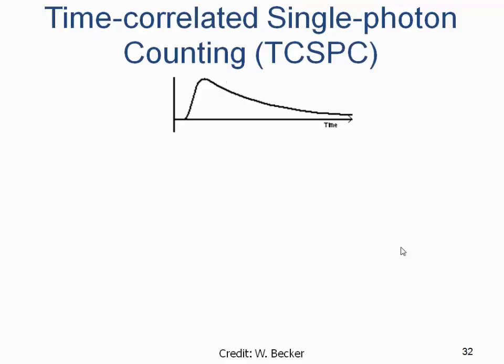We need amplification and we need speed. And this new idea came with another approach based on intrinsic amplification obtained in single photon detection. This is obtained in a technique known as TCSPC, or time-correlated single photon counting. The idea is very simple. You send a laser pulse, and then you make a single measurement. This measurement corresponds to a single SPAD, or single photon detection.